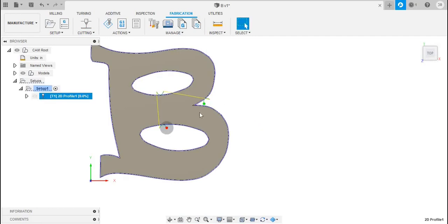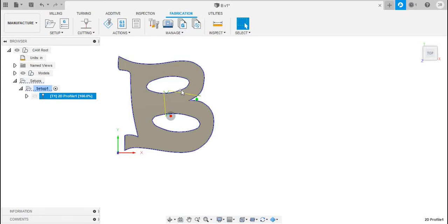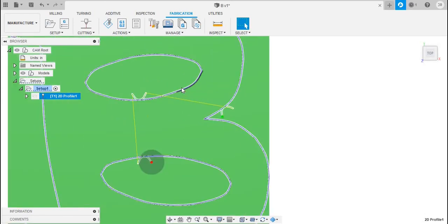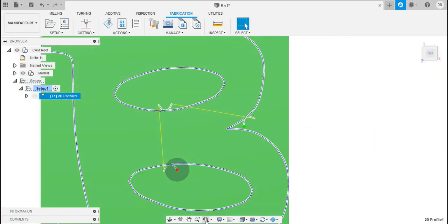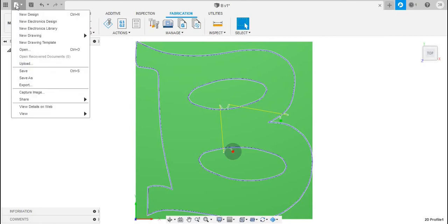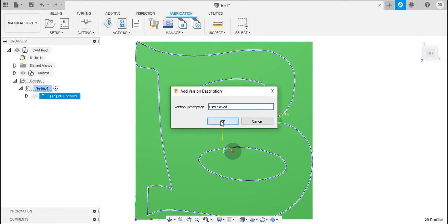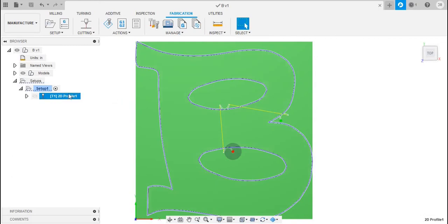There we go. I'm going to be seeing the entrance and exit points. I'm going to zoom in on this. This is the actual line of the object that we drew using the text, exploding text, and here's the actual toolpath. So it's on the inside there, and in this case it's on the outside. And notice these lead-ins and lead-outs, those will work perfectly fine for what I'm doing, so I'm going to fit here. So excellent. Now I'm going to save it once again. I'm going to just save over everything that I had, and then I'm going to come through and do the post-processing.